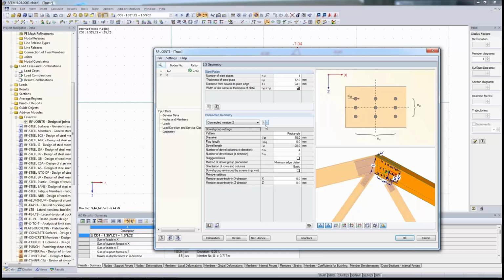Diameter and everything else. Then the bracings. I can also define 12 millimeter dowels just to have it similar on both. 6 dowels in X direction. As you see, this brace is pretty slim. Maybe it would have made sense to make it a little bit thicker, at least in its Z orientation. But now we go with that. We try to go with that.